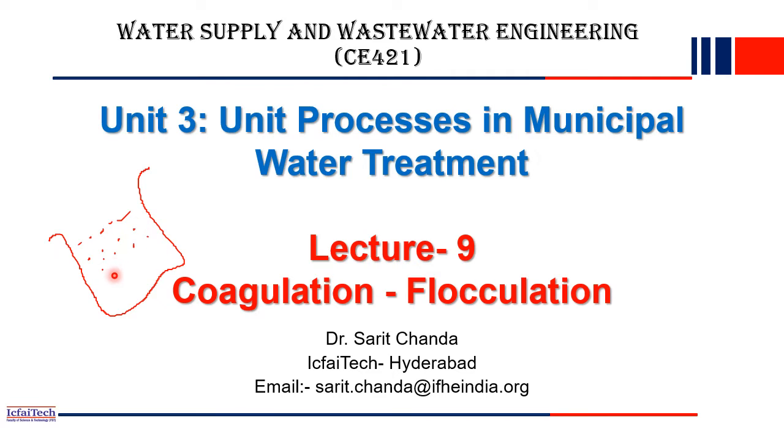No matter how much time we keep the water in a rest condition, these particles won't settle down. So we have to do some secondary treatment, where we remove all these small suspended particles also. We have seen the properties of suspended particles, and based on their properties we apply some extra chemicals that we call coagulant.